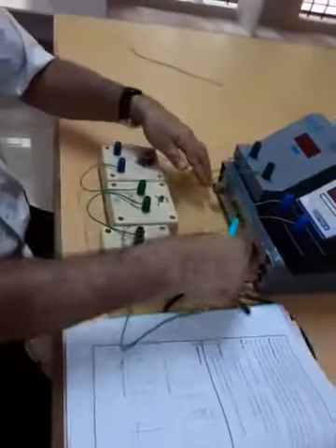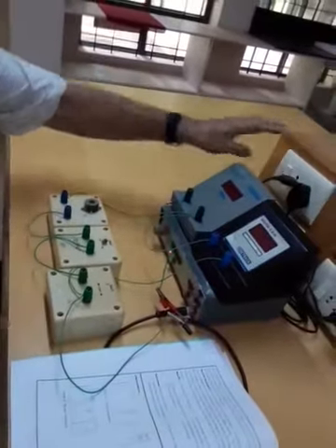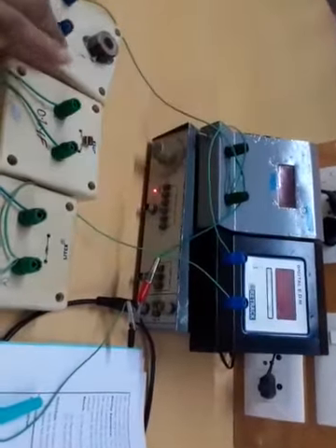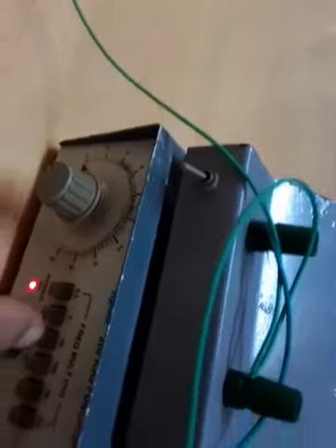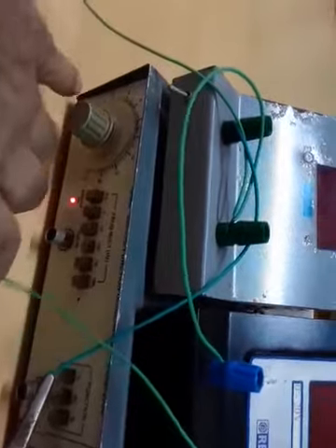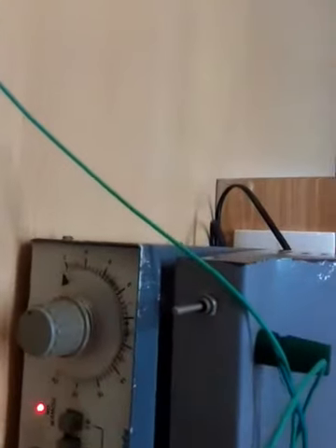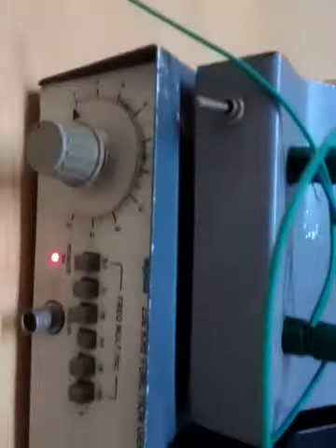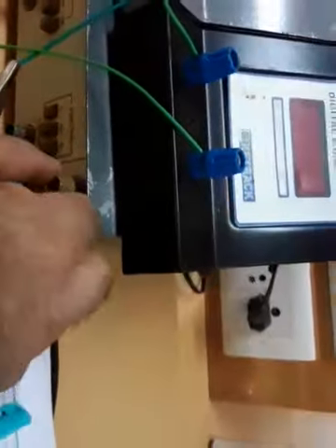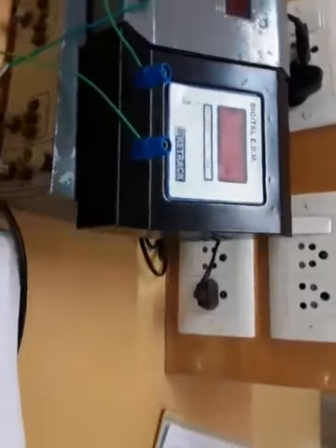Now, since everything is done, I can put this on. Here we have the frequency knob where I can keep the frequency at 2, and by pressing here 100, it will give you the frequency 100 into 2 becomes 200. And in this experiment, we are utilizing the sinusoidal wave. So we require to press this, and this is the amplitude of the signal.